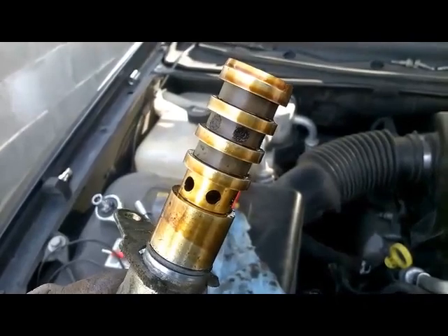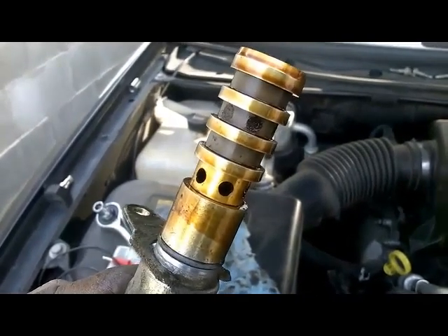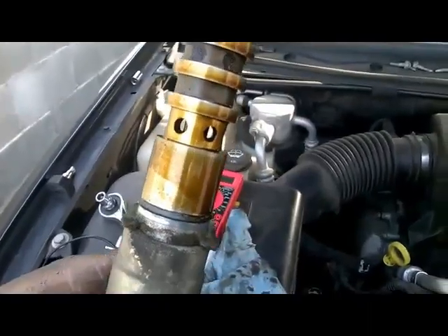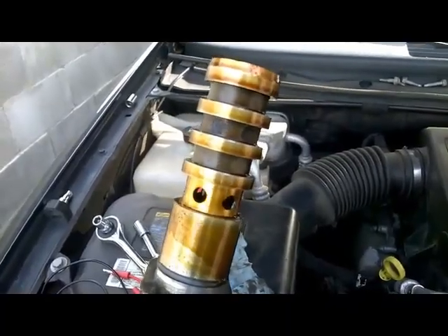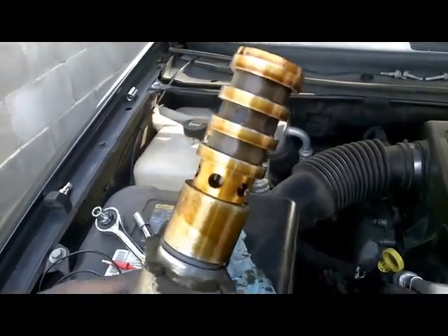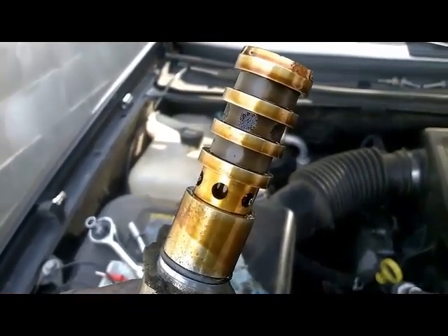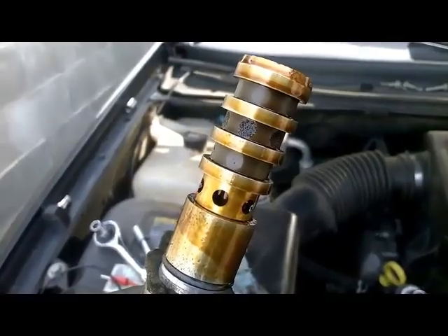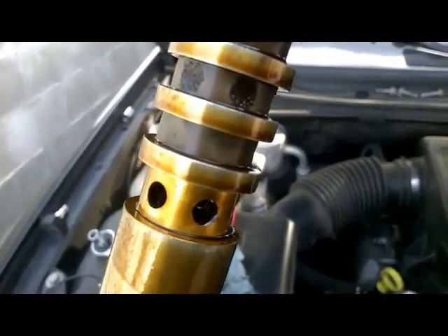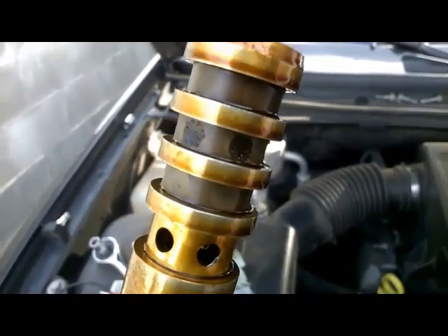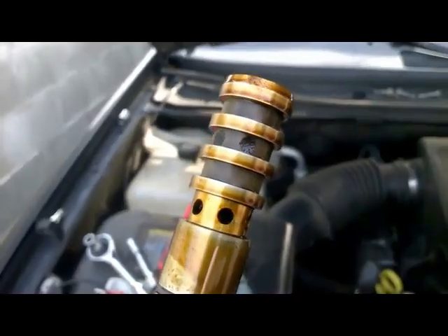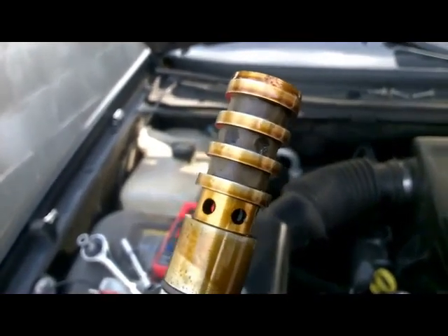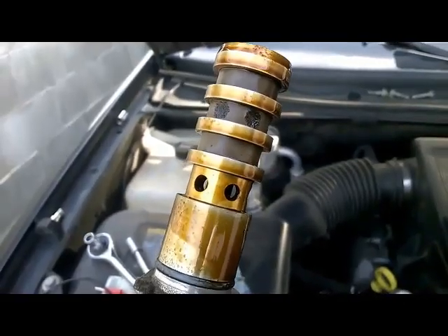So the best thing, as a technician, I would probably recommend the customer replace this solenoid with a brand new one. But if you're on a tight budget, the second best choice is to try to clean it thoroughly with either brake cleaner or carburetor cleaner, and clean these screens, which are restricting the oil flow, which is not providing full function of this camshaft solenoid to this engine, which is causing this rough idle.